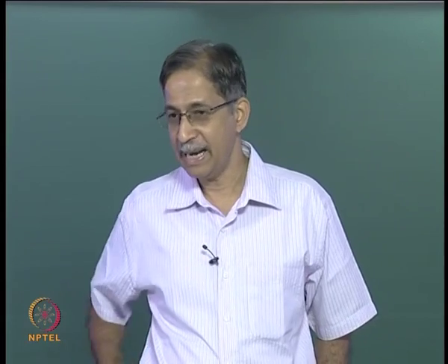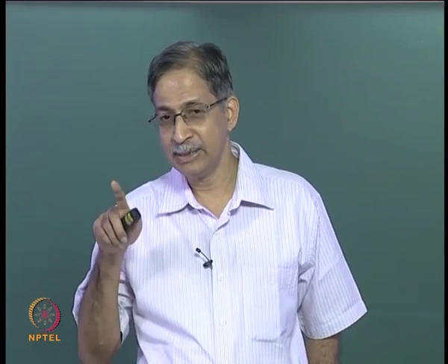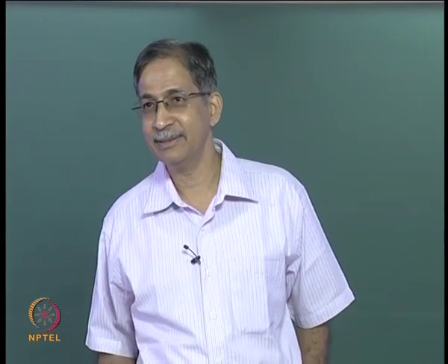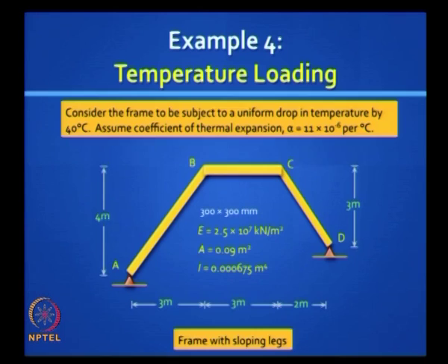You will find that they are almost identical. This is more accurate because you are accounting for axial deformation. We will do the same problem by the reduced element stiffness method, where we ignore axial deformations, and compare the results. Okay, here is one last problem, a really interesting problem.